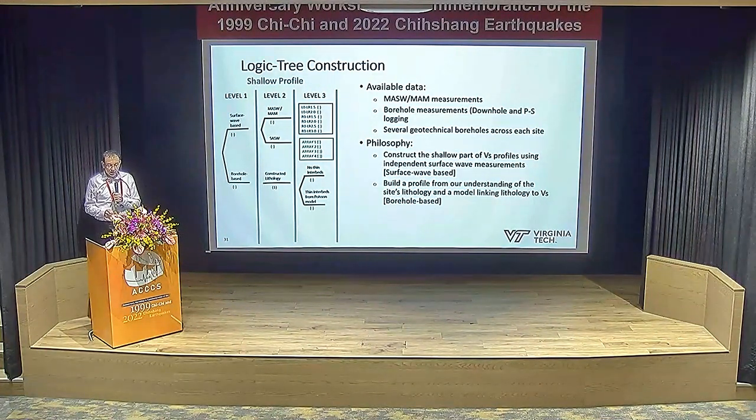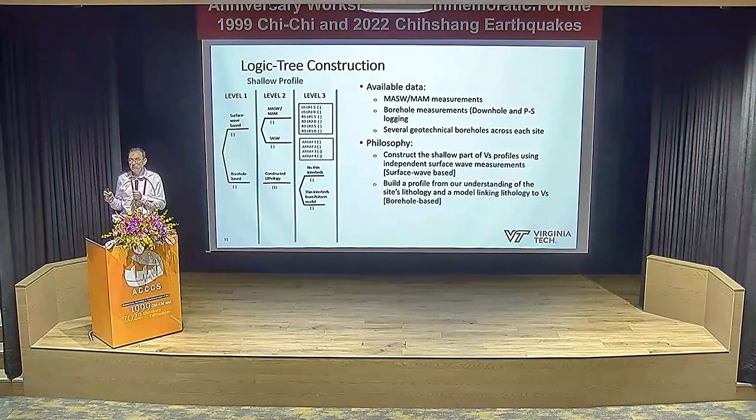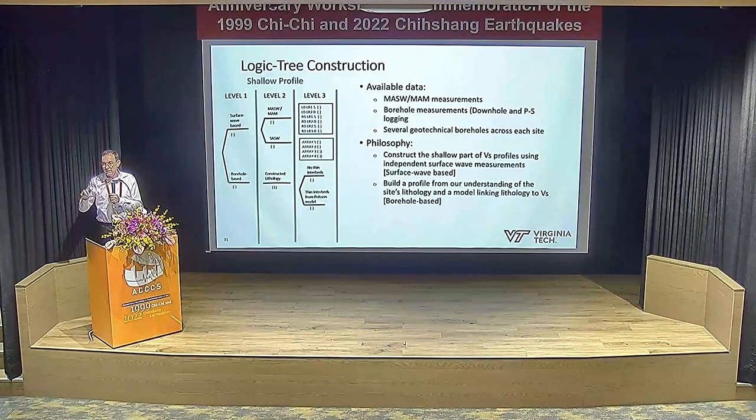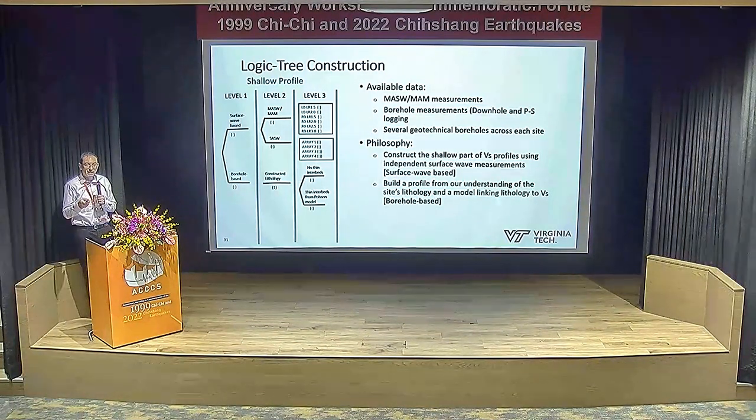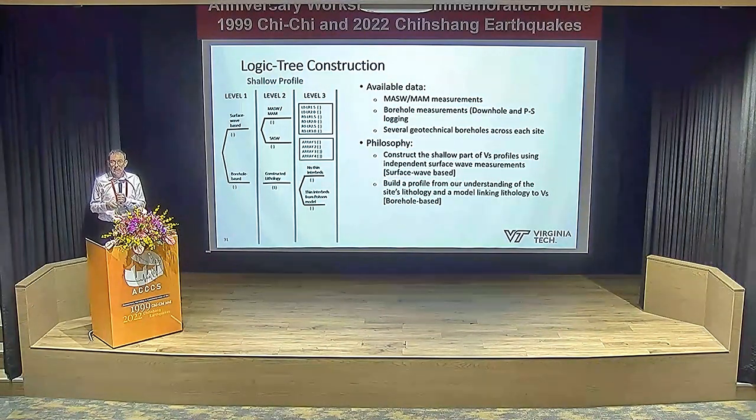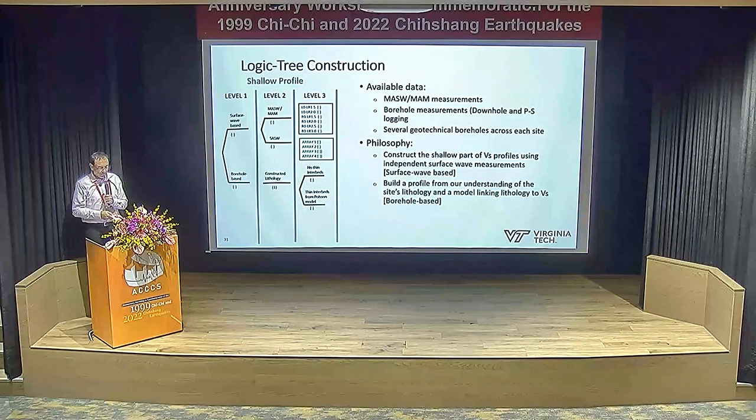In addition, I should mention that the study at INL had 5 different target locations, so we're looking at 5 sites that were located across the whole Idaho National Lab. We also had several geotechnical boreholes across each site, so we could develop a good stratigraphic profile and have an idea of how this stratigraphic profile varies across each one of the sites.